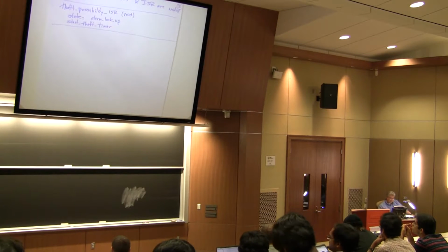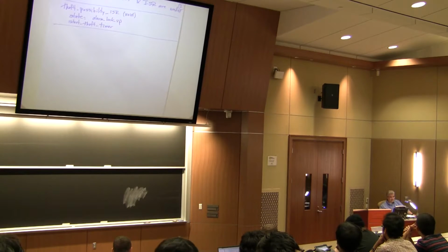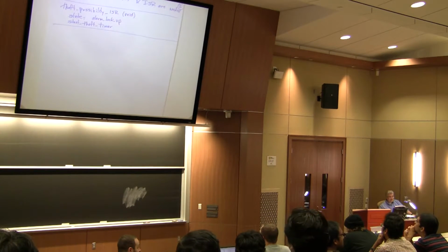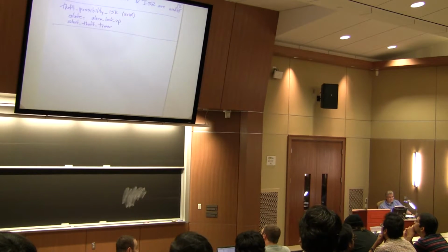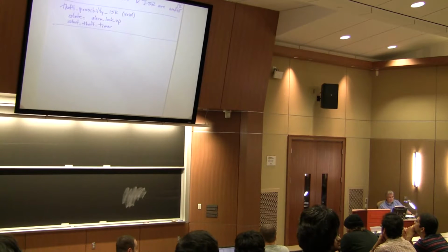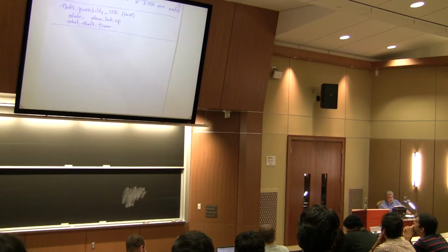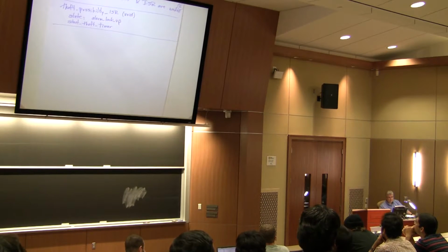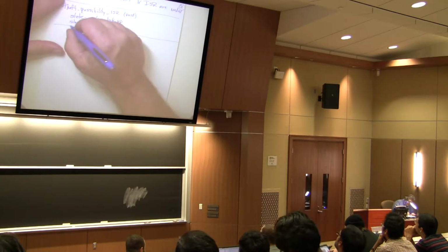What's another one? Disable all the other interrupts. Oh, hold on, you just said something so fast I didn't understand. Disable all the other interrupts which are not required. Okay, do we really want to disable all the interrupts? Except the timer interrupt, the other interrupts will be disabled, because suppose anybody presses some other button, it will go to that state. Well, is that a bad thing? Yeah, if it is in the lockup mode, it should not go anywhere else. All right, so you're saying we should disable interrupts.